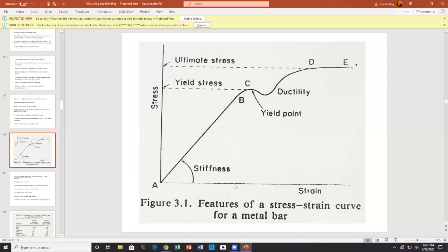The temperature rise, you got the material broken. Okay, the material breaks, comes out. But the temperature rise of the inefficient energy may be high enough to melt the material or cause the material surface characteristics to change, and the material freezes back together again or agglomerates back together again. That's a really pain in the neck. You got the stuff broken, but it fuses back together again as part of the release. Isn't that a terrible situation?